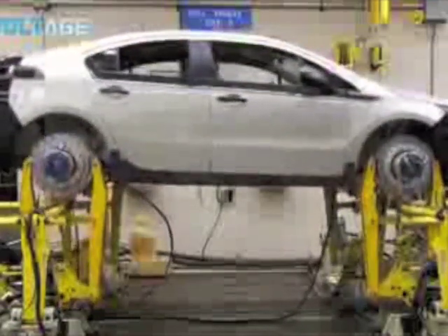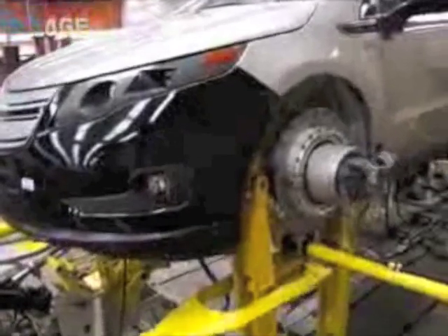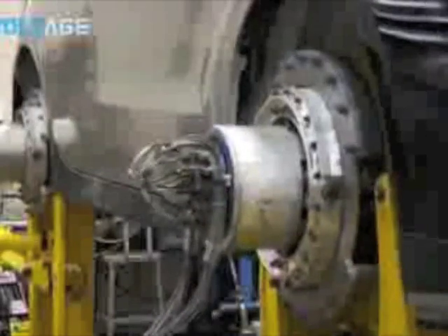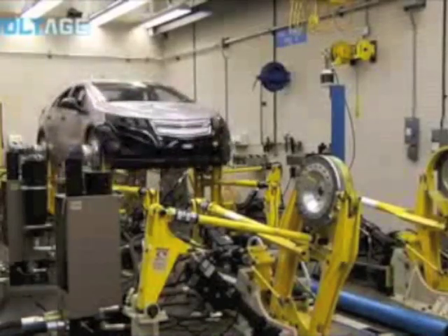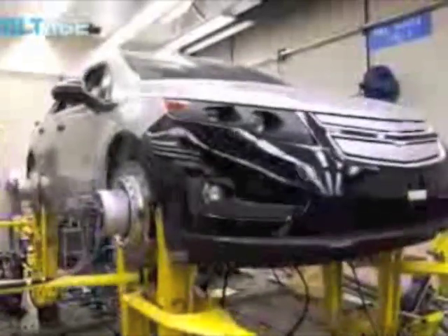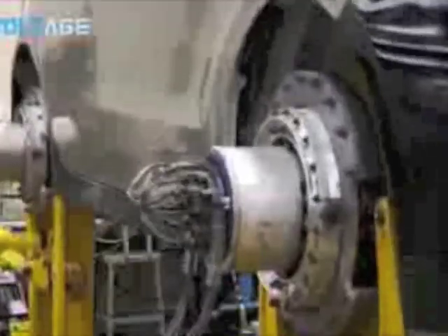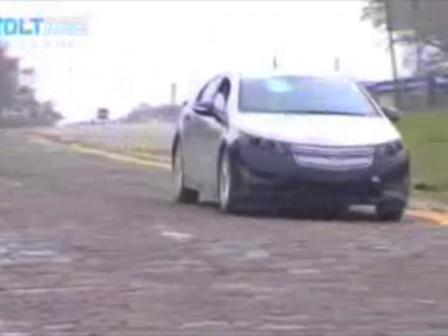Here is a car mounted on a shaker system. As you look carefully, you'll note that the low-frequency motion of the shaker is passed through to the car's body, but the high-frequency motion of the shaker is not passed through. This is the proper role of the suspension. It is to pass the low-frequency motion, which corresponds to the contours of the road, and to reject the high-frequency motion, which corresponds to the roughness of the road. Thus the car suspension acts as a filter, passing one set of frequencies and rejecting another.